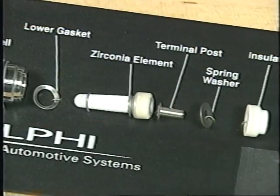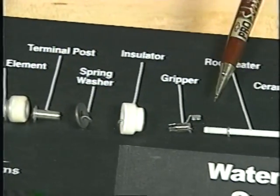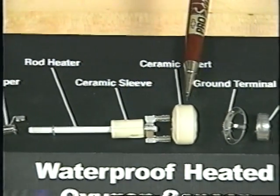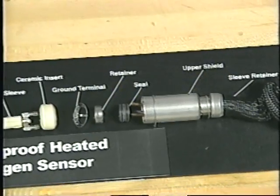First, let's take a quick look inside. Just like a spark plug, an oxygen sensor has a lot of ceramic components in it. The zirconia ceramic tip extends out into the exhaust stream. There's also a ceramic insulator, a ceramic heater and sleeve, and a ceramic insert. They're all housed in a metal shield, where you'll also find the entry point for the electrical wiring harness. Those ceramic components are easily broken if the O2 sensor is dropped, so you've got to handle them with care.